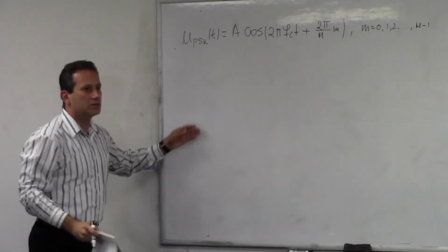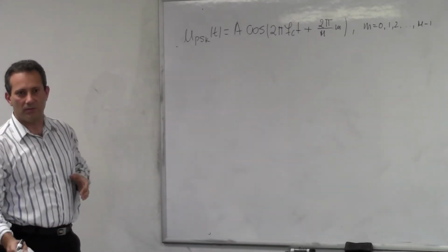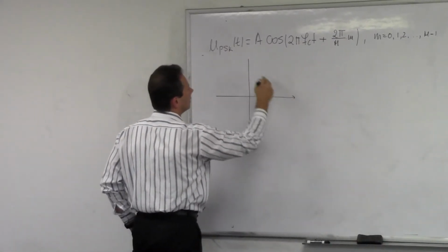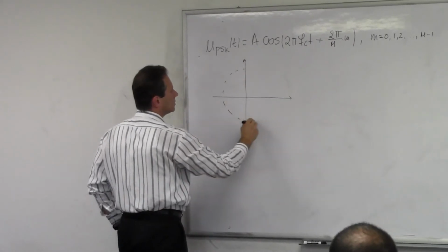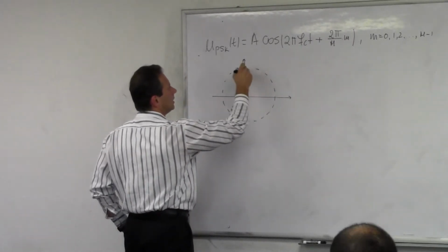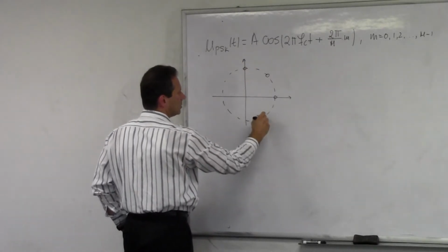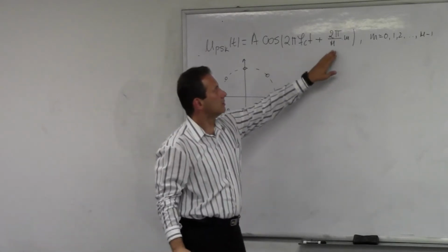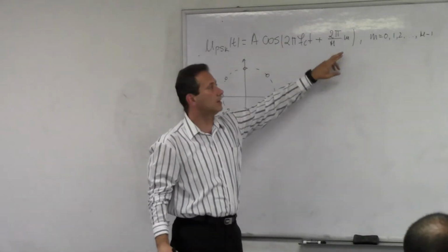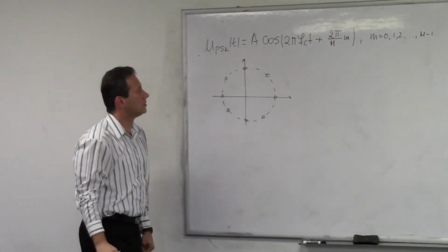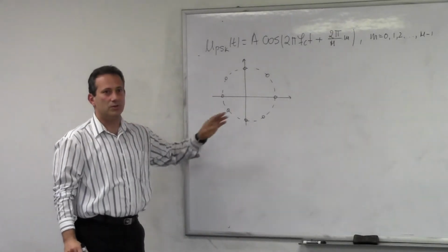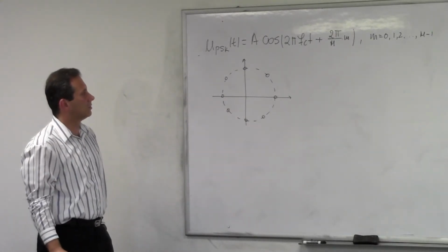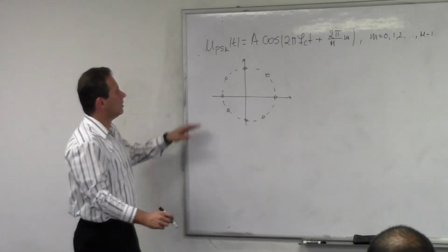That gave us a constellation of symbols which all resided on the same unit circle. Remember, they were all on the same unit circle. Let's say in the case of 8-PSK, those were the points of your constellation. And this 2 pi over M was an angular separation between them, and then there's capital M symbols, where depending on how large M is, you can modulate a certain number of bits on a symbol. We did this last time.